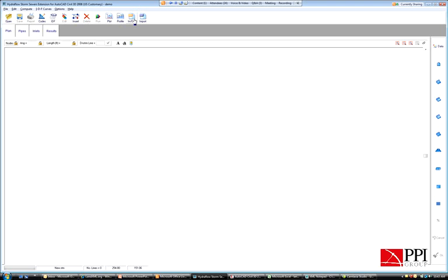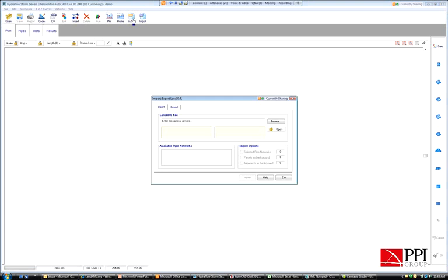And I guess that choppiness, I thought I was opening, but I think it's just my Camtasia keeps throwing me. So to bring stuff in and out of LandXML, you can see along here, a typical, pretty easy to understand toolbar. This will allow you to edit that network once you're in there. My preference is definitely to still draw my networks in Civil 3D and bring them into here. The import process is pretty harmless. But to bring the XMLs in and out, I come up here to the XML in and out. Brings me into here.